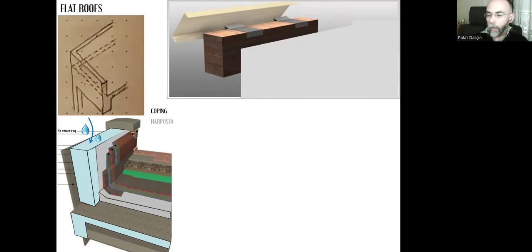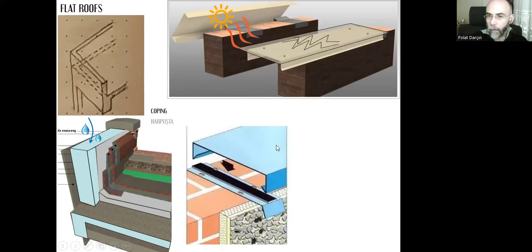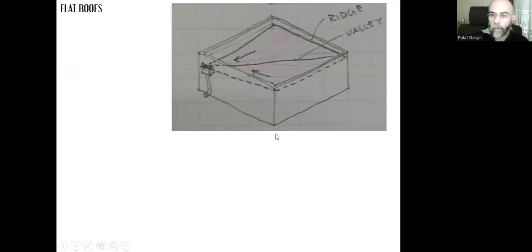That's why, again, you need to prefer this interlocking method to place the coping over the surface of the parapet wall like this. You can have this long sheet of coping, and you can first fix strips on the surface of the parapet wall like that. These strips, and you can fold the coping into these hook-like ends, and you can place the coping using these hooks like this.